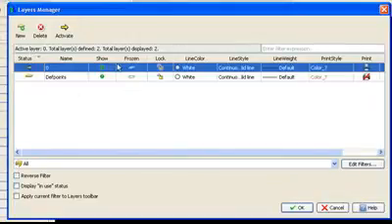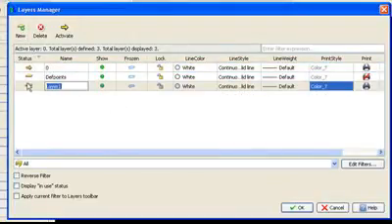Every time I create a new layer within DraftSight and I click on new, these settings that are right here, the show, hide, freeze, lock, color, line style, and line weight, will all be taken from whatever the active layer is. So if this is the active layer, you see my active layer is white, so this layer will be white. Every layer I create now is going to take the same properties as the active layer.